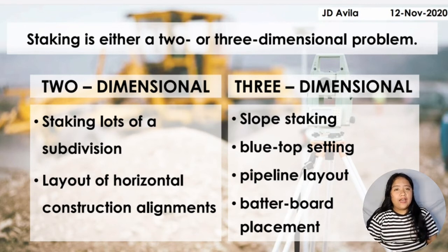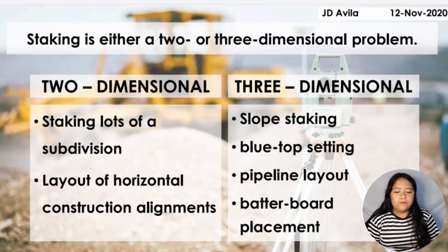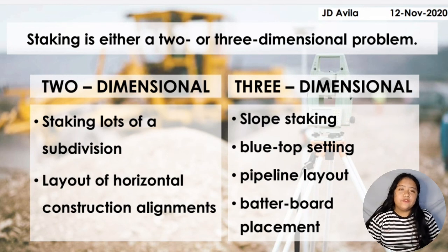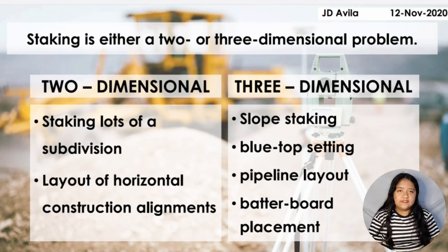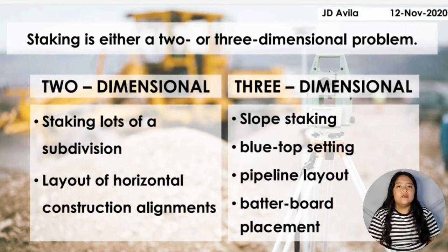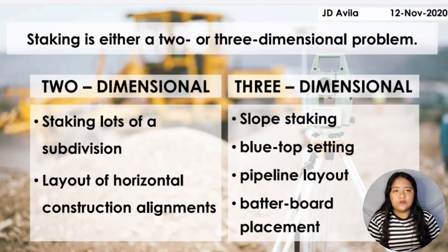With a total station having robotic capabilities, the instrument will swing to the proper azimuth without any further operator intervention. With a high order of accuracy using total station instruments, stakes quite distant from the instrument can be laid out, and thus many points set from a single setup. In fact, an entire project can be staked from one location. This is made possible in many cases because of the flexibility that resection orientation provides in instrument placement.